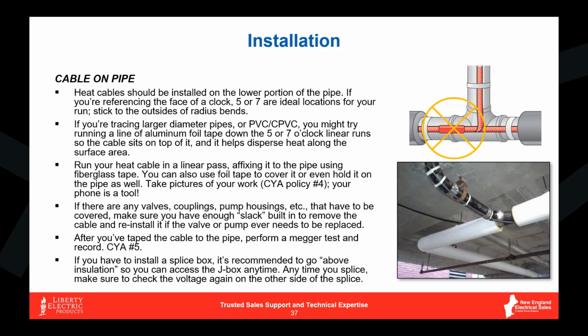Generally when you're doing stuff like, say, valves or obstructions that are inside of the piping runs, you've got to allow for that and put a little bit of slack in that run, so that if the mechanical guy's got to come in here and pull out an OS and Y valve or something like that, they're not going to care about the heating cable. They're going to try and get that thing off the pipe as quickly as they can without cutting it. But that's not to say it doesn't get manhandled and damaged and scraped and cut, all those types of things. So if we allow them a little bit of slack to say, hey, just take it easy when you take that cable off the pipe, and don't worry, we'll put it back on after. Just leave it dangling there and don't damage it in the meantime.